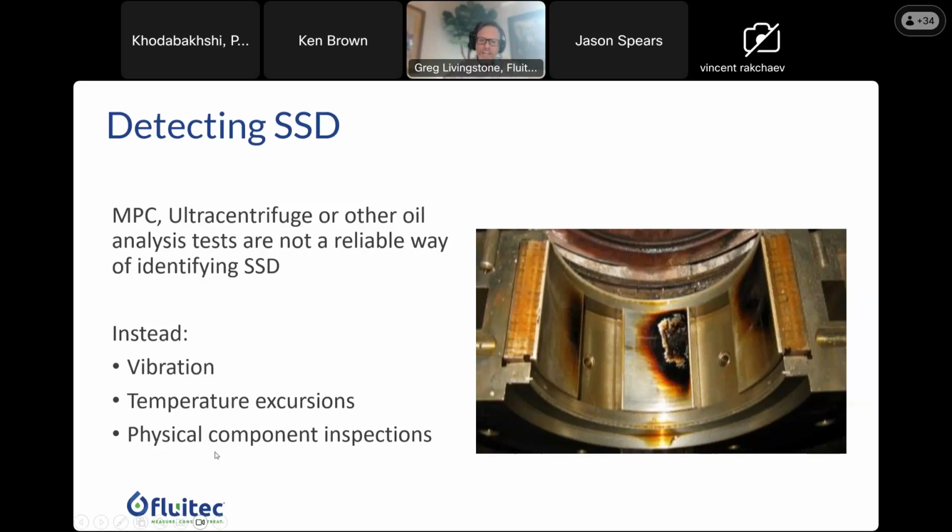And also during any overhaul, it's super valuable to visually inspect all your components, all your oil wetted components. And often this is where we'll see signs of deposits here on the bearing surface. You could see varnish happening throughout the rest of the system as well. But if we start to see high levels of deposits in the bearings that are correlated with maybe some bearing wear, you should investigate maybe shear stress deposits a little more carefully.